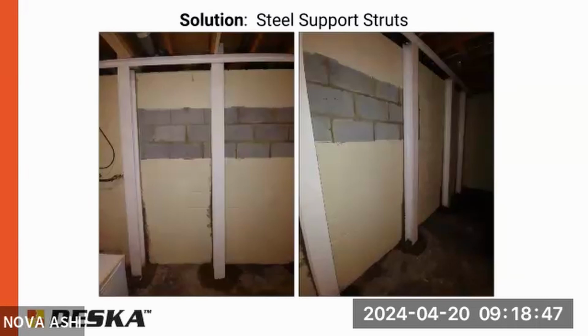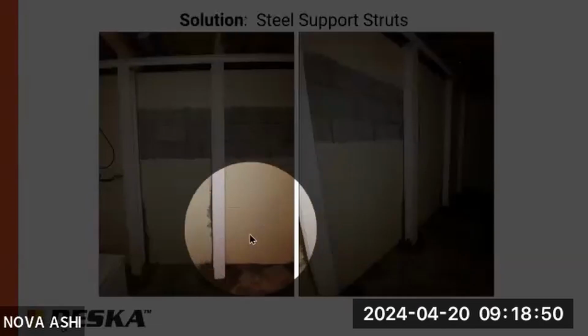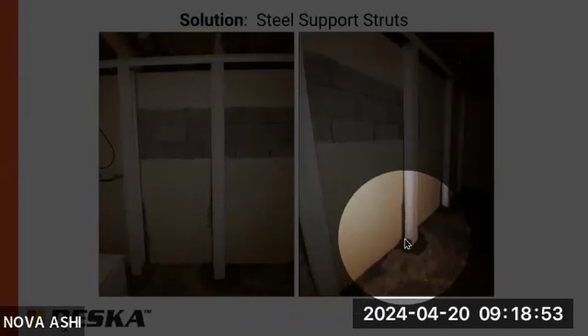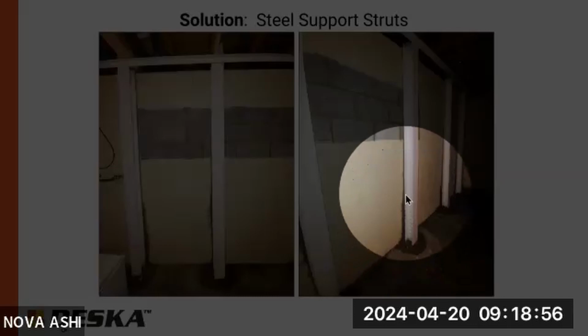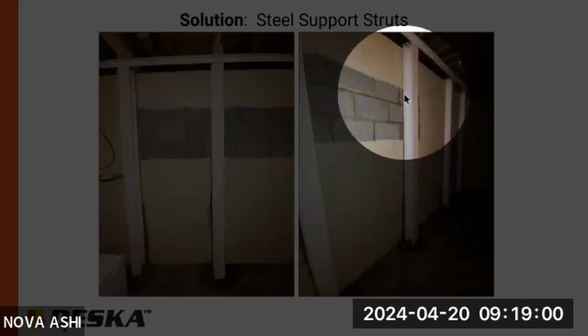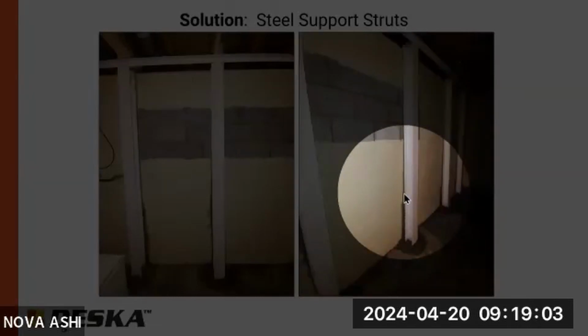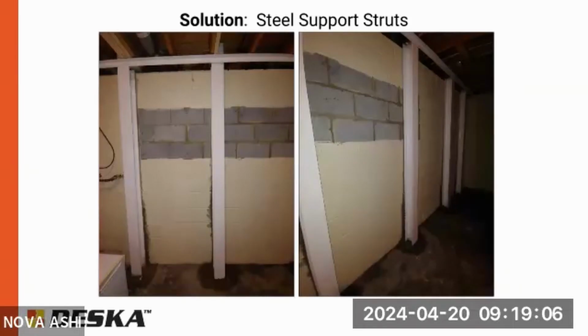Here's an example of what they actually look like, and as you can see at the bottom here, there's a gap that has been grouted with cement, and as you come up the wall, it disappears, and as you get to the top of the wall, usually it will widen again. So they're not the ugliest thing in the world, but you'd prefer not to have them in your basement, obviously. And they typically eat up 4 to 6 inches of space too. So, if you can get away with carbon fiber straps, that's ideal. These are more expensive. And if you have a 30-foot wall and you're going to lose 6 inches, you just lost 15 square feet of your foundation there. So you can finish over this, but your wall is going to have to sit in a little bit farther.